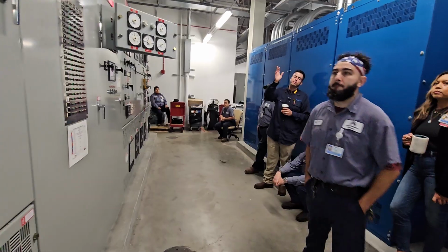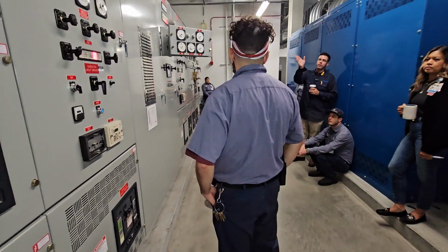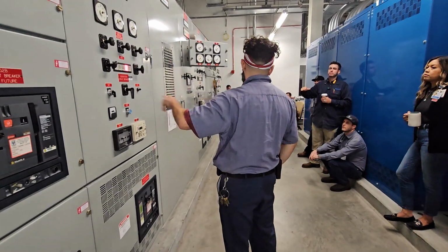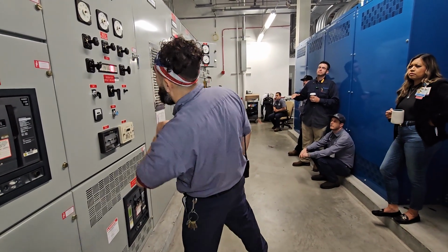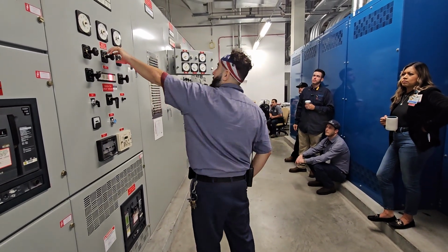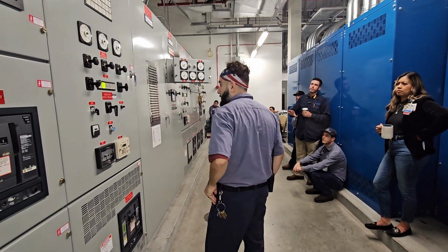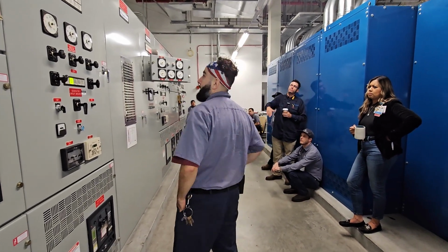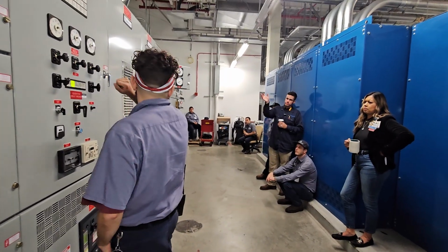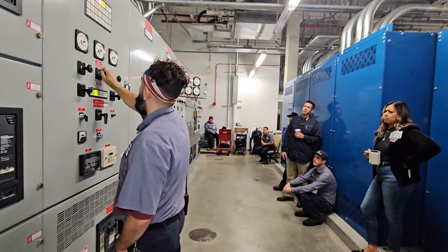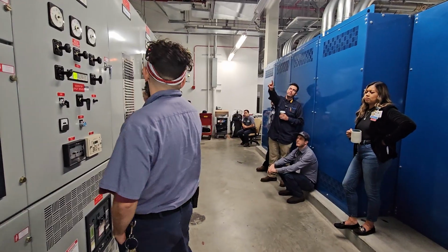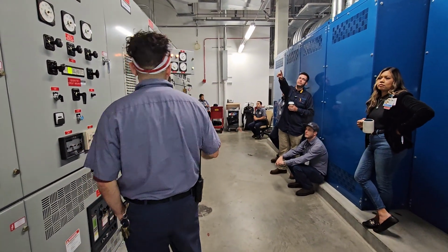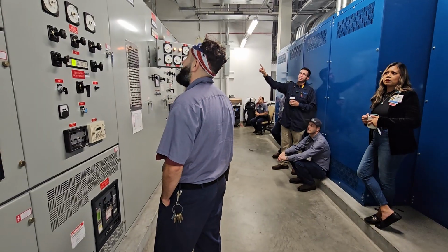Shut it off. When you go from run to auto, it's gonna open the breaker, but the generator will stay running. All of this will do automatically. I just gotta switch it to auto. Yeah, switch it to auto, see what happens. The breaker opens, generator is on cooldown. Now go all the way to stop reset. Go to off first. Generator is not available, but it's still on cooldown. That's why you have a red light flashing and a green light flashing.